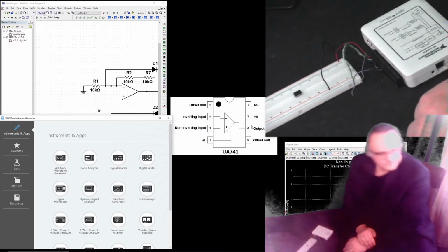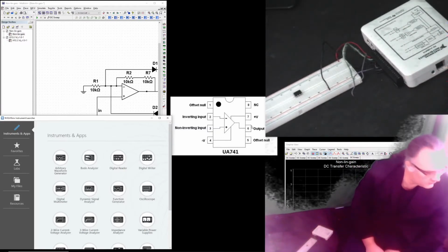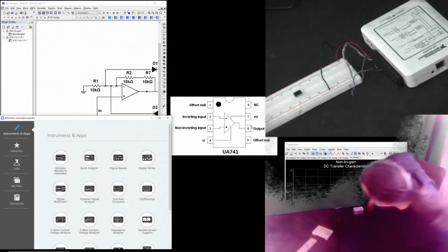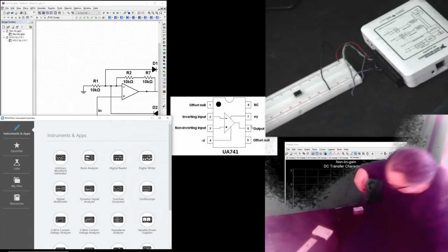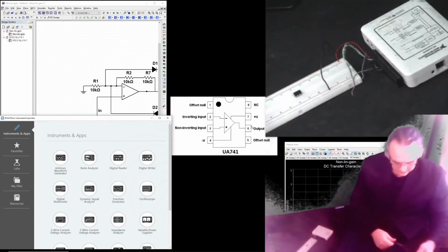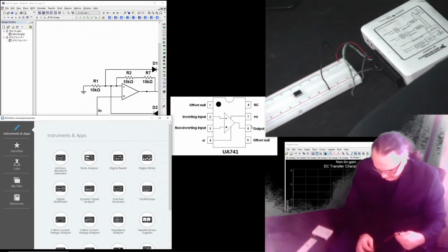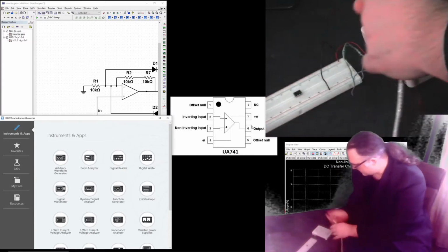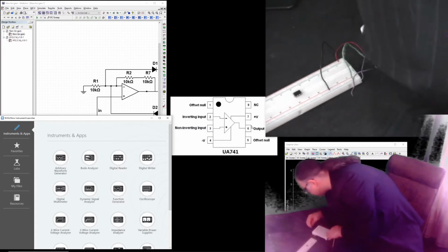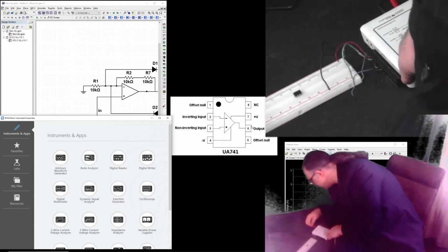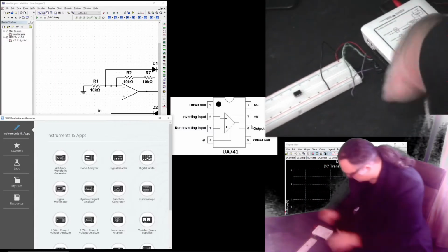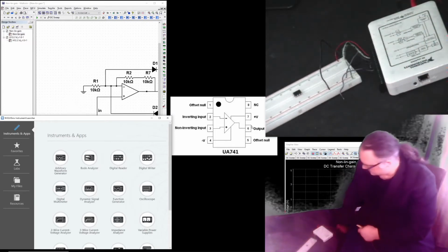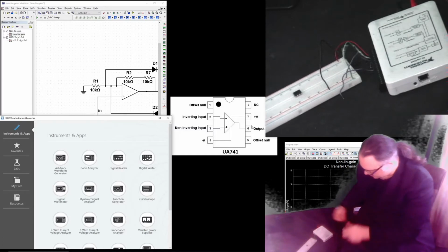Now I need to build the circuit, so it is always good to measure exactly the resistors that you're putting to avoid mistakes. So you can use MyDAQ for this, in digital multimeter configuration. So I'll connect now MyDAQ.